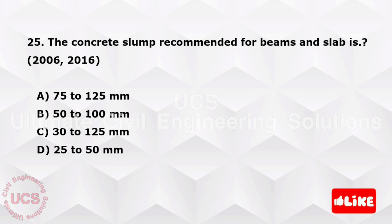Final question. The concrete slump recommended for beams and slab is. Options are option A 75 to 125 mm, option B 50 to 100 mm, option C 30 to 125 mm, option D 25 to 50 mm. Answer is option C, 30 to 125 mm.